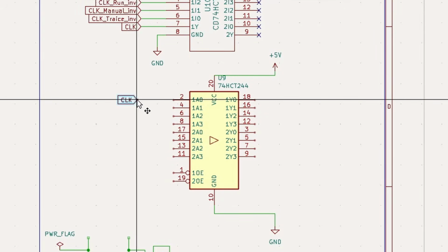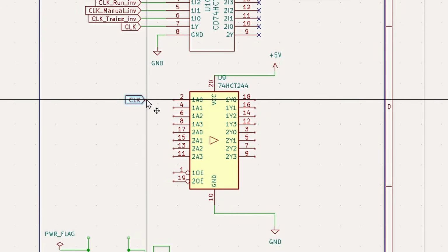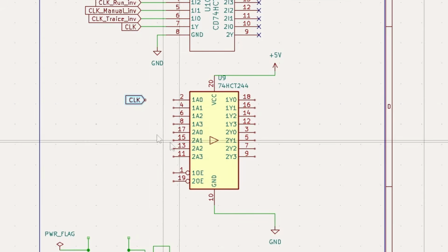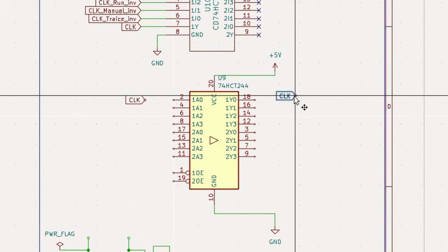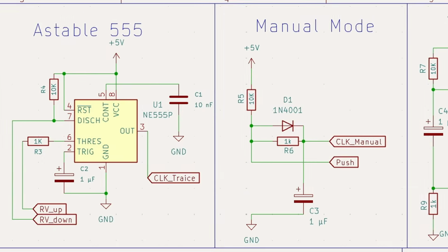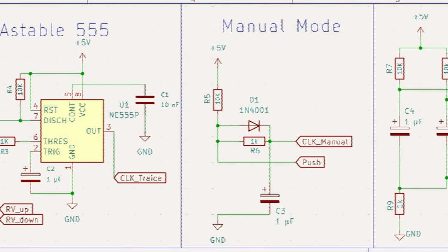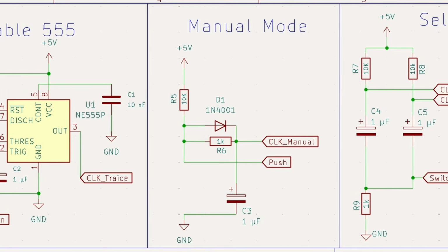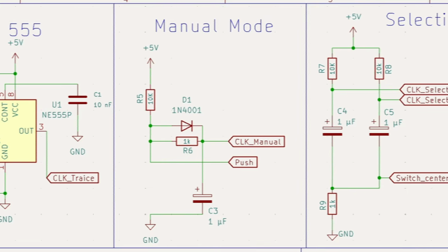Instead of physically drawing every wire across the schematic, I could simply give a signal a label with a name. Anywhere else that same label appeared, KiCad would treat it as exactly the same electrical connection. And that made a huge difference.